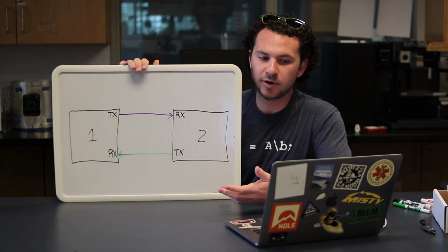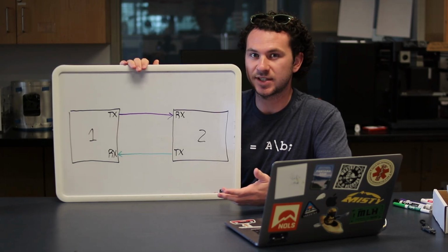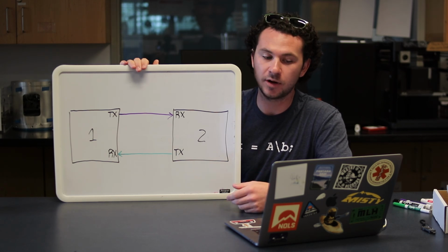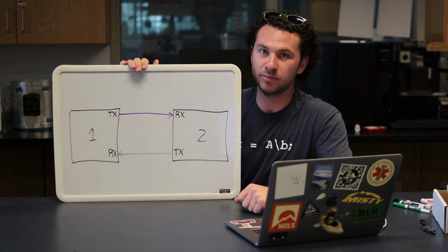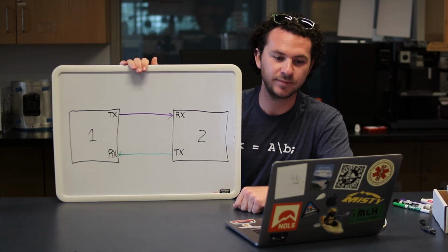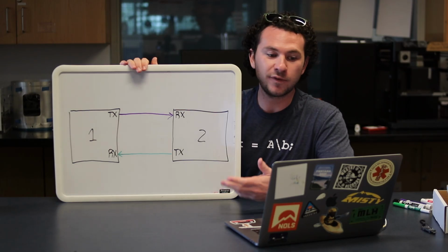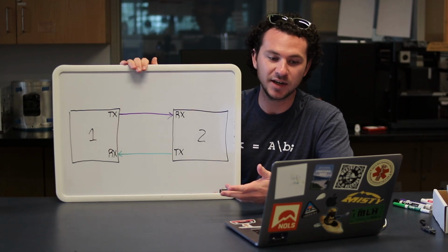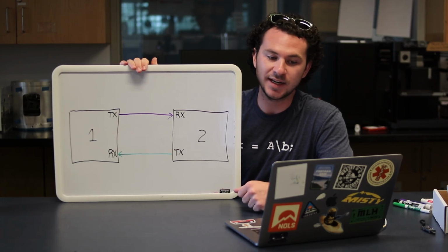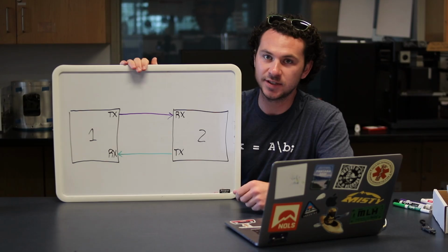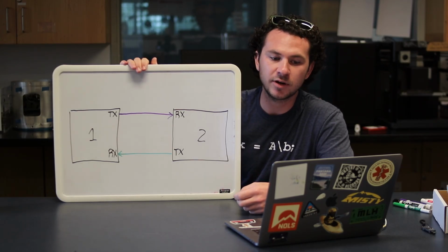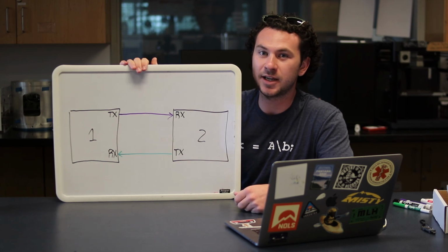Finally, we get to a serial protocol that's a bit different than anything else we've discussed. The Universal Asynchronous Receiver Transmitter, or UART protocol, is an asynchronous serial protocol versus the previous two synchronous protocols we've discussed. Remember, that means that UART forgoes a shared clock wire to keep the devices in sync with each other. It instead relies on strict standardization and timing of messages.